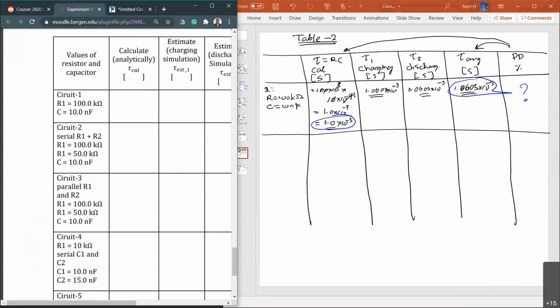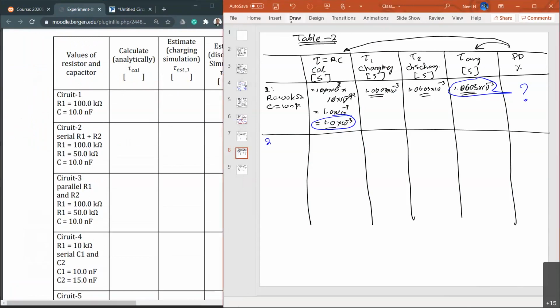So let's build circuit number 2. Circuit number 2, what is the difference? Anybody have any problems? Everybody okay? Measuring the time constant directly. Now you can see how easy it is to analyze this circuit by using the oscilloscope, right? That's the lesson we're learning with this experiment, because if you don't have an oscilloscope, you have to measure time and voltage and then make a graph, linearize the graph, and it's a lot of work. If you have the oscilloscope, then it is very simple.